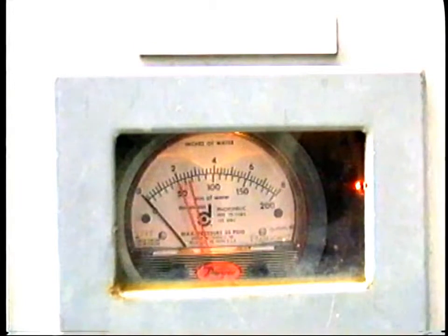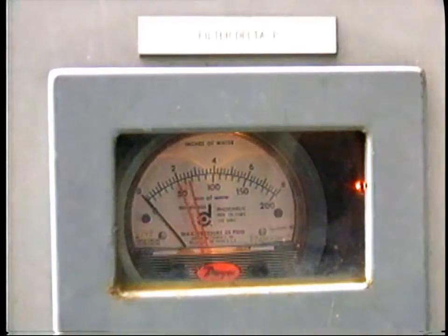On standby or peaking units, this task can easily be performed when the unit is out of service. However, on continuously operated base load units, automatic continuous filter cleaning is usually installed. The provision of clean air is absolutely essential, as the ingress of dust and other particulate matter may block cooling passages and may even cause grounding and consequent damage to the insulation.